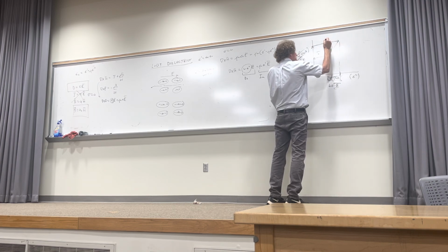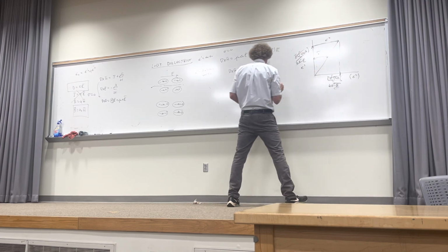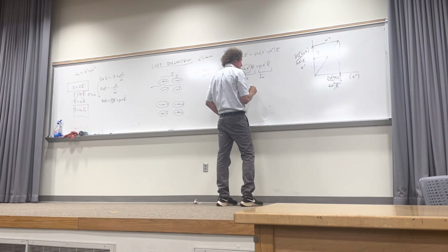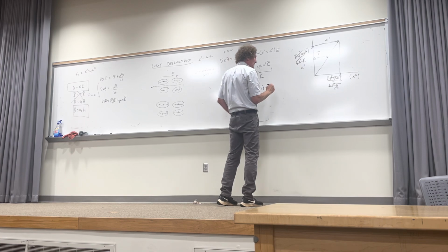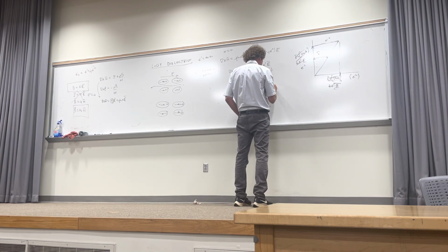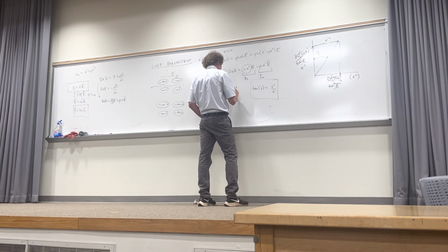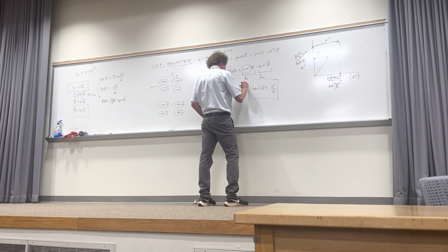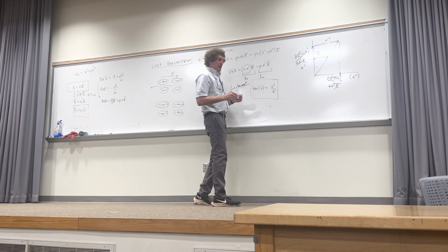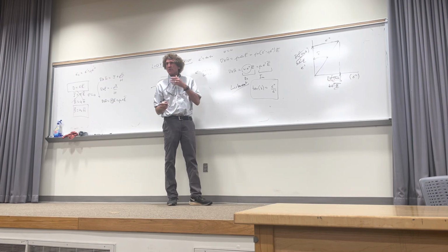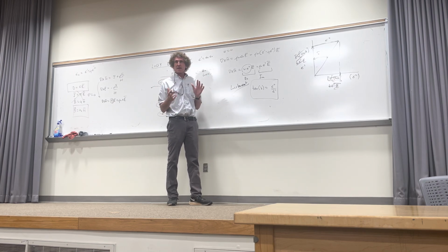This dimension is epsilon double prime, so you can see, and this is the important part, if I take the tangent of that angle, that's opposite over adjacent, or epsilon double prime over epsilon prime. And this is called the loss tangent. Now, the only thing it does is when you have material science information and you're doing designs, here's the deal.